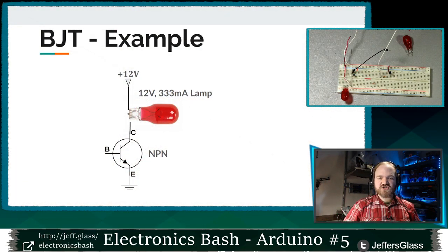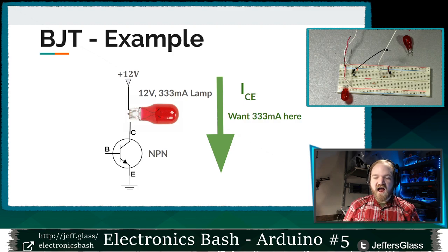So remember that to turn this on, I'm going to want to put about 300-ish milliamps through here. And if I'm being a little bit vague about the math, it's because, remember, this is a light bulb, right? It's a glowing piece of tungsten. I'm not going to expect that the manufacturer has made this exactly a 4-watt light bulb. It's going to be 4 watts-ish, 4.5, 3.5, who cares? It's a tiny, shitty light bulb.